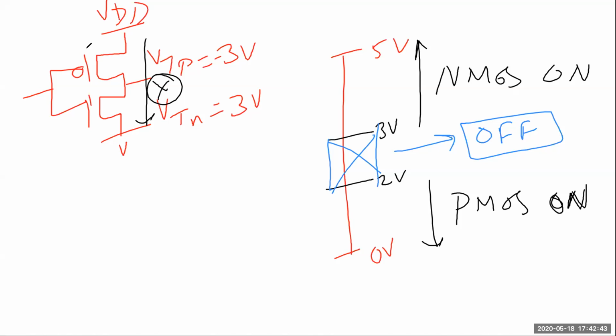So, in my graph, I showed it as if it is like two inverter characteristics, right? Yes. But I think you'll not get that slow, because none of them are on at both times. So what will happen is you'll get VDD all the way to 3 volt, and then boom, like 2 volts when the input goes above 3 volt. And on the way back, because you have a capacitor charged to VDD or discharged to ground, the PMOS doesn't go on till you get to 0.2 volt, and then the PMOS just takes over and charges it up all the way.